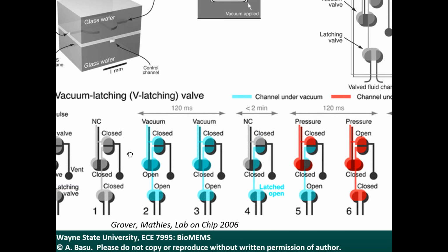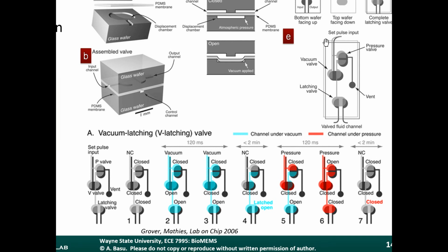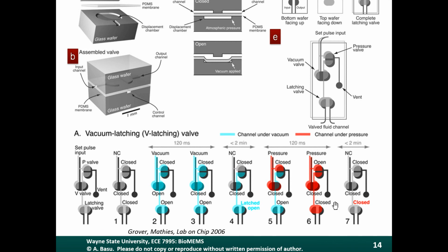So as a result, you can build what's called a fluidic latch, where you can put a pulse input on here, meaning like, just a high pressure back to low pressure, square wave like this, and you can switch the state of the valve from the low state, from the off state to the on state. In other words, if we're talking about it in pneumatic terms, from the open state to the closed state. So this bottom part of it, this is where the fluidic channel is, okay? You just want to control flow between the fluid channel, this left inlet and the right outlet here, and this is the valve part of it that controls it.